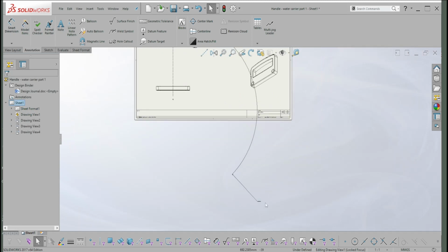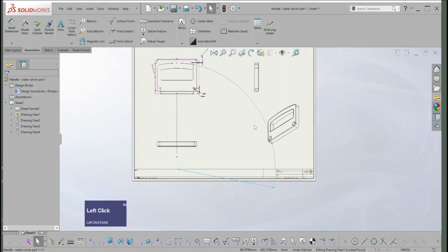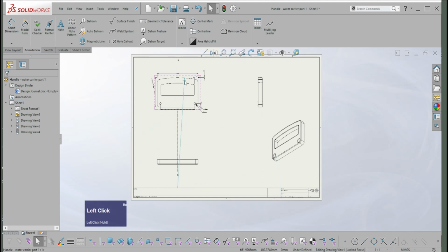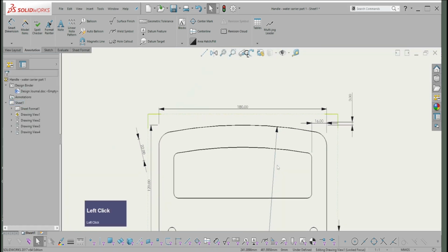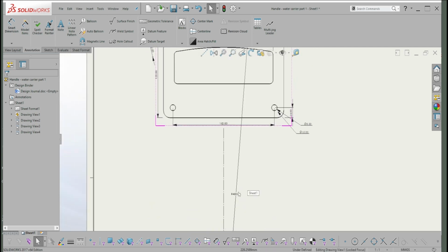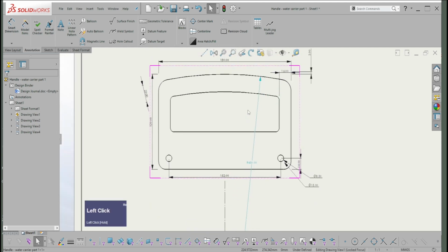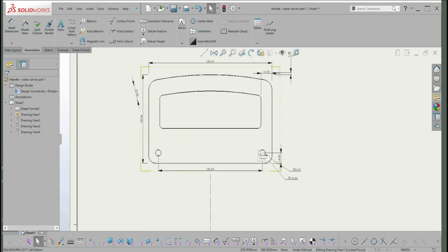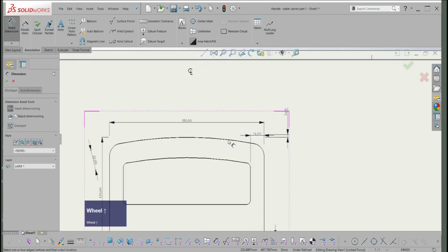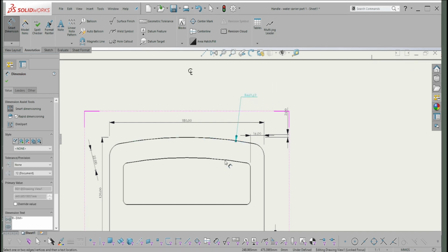For instance, I went in later and I put in a radius here, which I can drag out. And I'm not really even happy with the radius dimension here, because it takes the radius all the way to the bottom with this long line. I've got to go and adjust that line, take off center and do all sorts of things. So I'm going to delete it, and I'm going to reintroduce it at the top like that. Much shorter, much nicer, much easier.